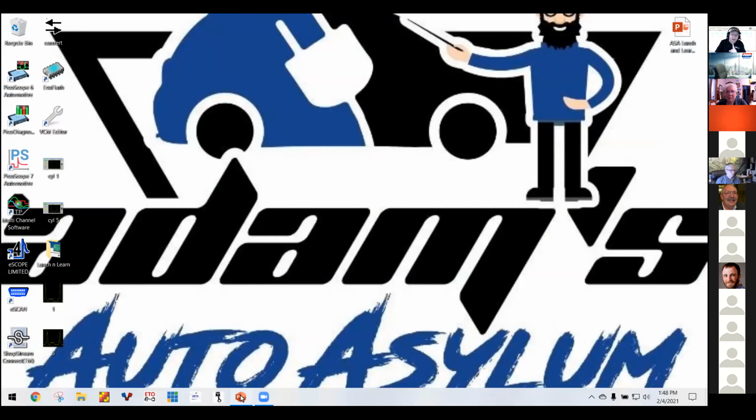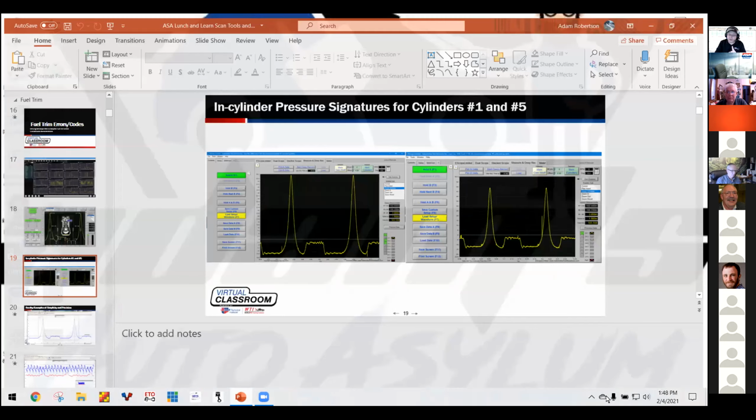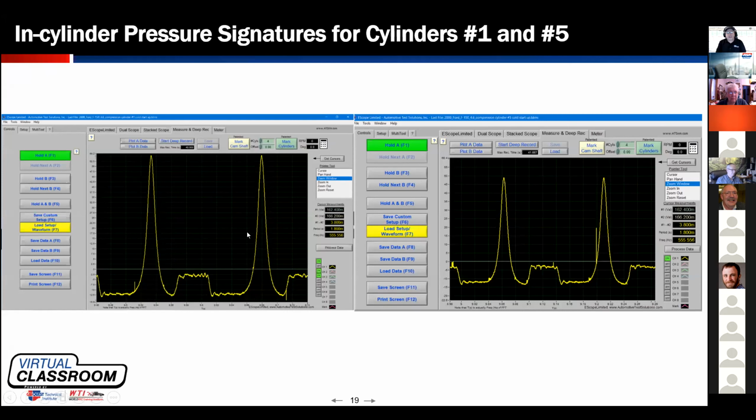And now I want to go back and talk a little bit more about this car. What I just proved to you on this 2003 Ford V8, 4.6, it's an F-150, is that the cam timing from one bank is mechanically different than the breathing from the other bank. By the way, looking closer, you'll realize the exhaust plateaus were similar. It was literally a cam timing issue.